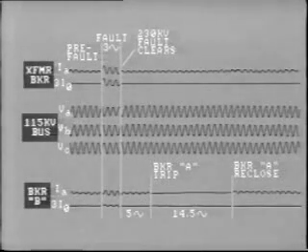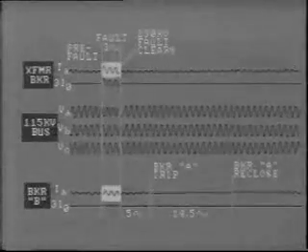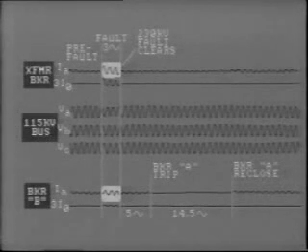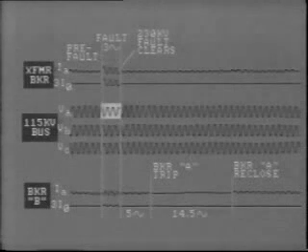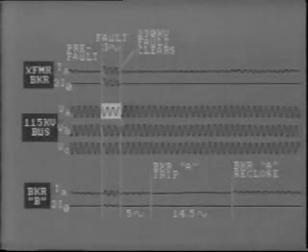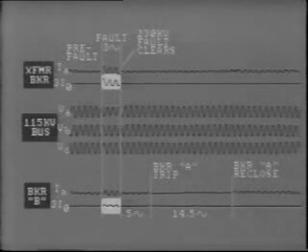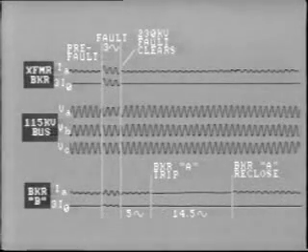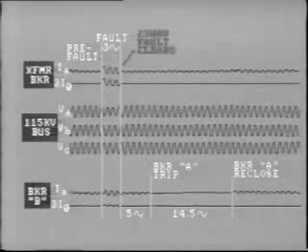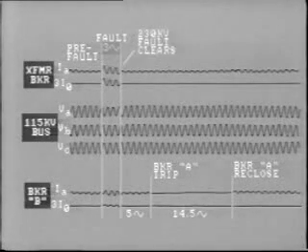The fault was on A-phase, as shown by the sharp increase in A-phase current through the transformer breaker and breaker B, and also by the depressed A-phase bus voltage. The presence of zero sequence in the breakers also indicates a ground fault. Tripping on the 230 kV system was correct, and the fault was cleared in just over 3 cycles.